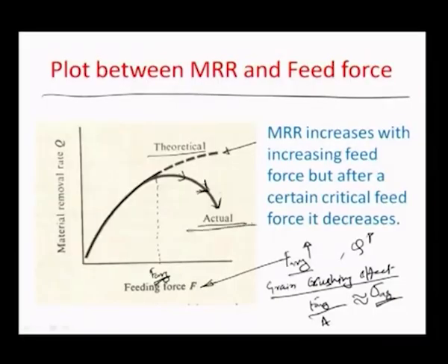go down, because they are themselves getting crushed. It is therefore reasonable to assume that because of this crushing effect of the grains, the number of available complete grains which come between, let us say, the tool head and the workpiece are lessened, and so would be the material removal rate. Therefore the actual trend of the material removal rate is shown by this particular illustration.